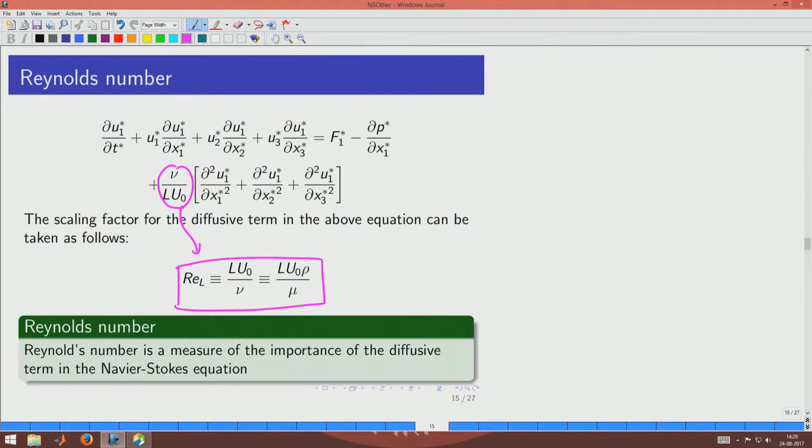You could see that the Reynolds number is naturally coming out of the Navier Stokes equation as a scaling factor in front of the diffusive term, and the units are wiped off because the non-dimensionalization is done for all the terms. It is also characterizing the problem, because we saw that it comes out of choosing the length scales, time scales, and velocity scales.